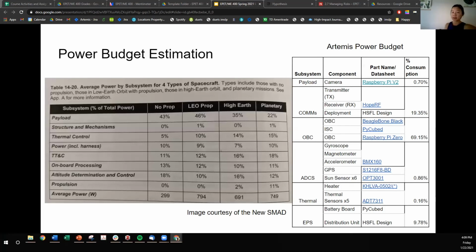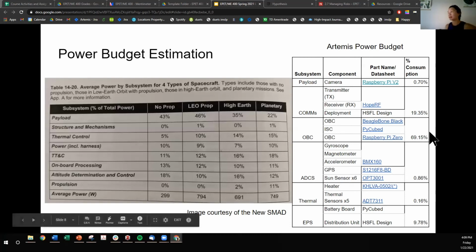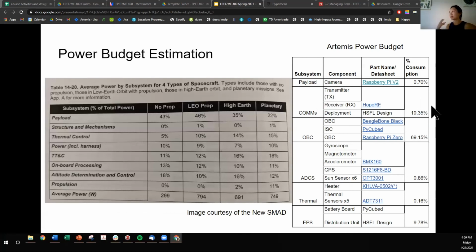Instead, the Artemis CubeSat kit has quite a bit of power for the computer and the radio, and that's by mission design because, again, there are two computers, and for the communication subsystem, we are always trying to beacon because we don't have a pointing system. We don't have an antenna that has to be pointing at ground. It's just tumbling and constantly beaconing. That's by design because our satellite is very simple. As we say, make it simple, stupid.